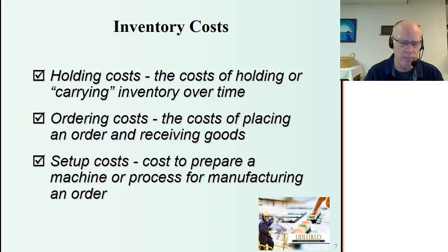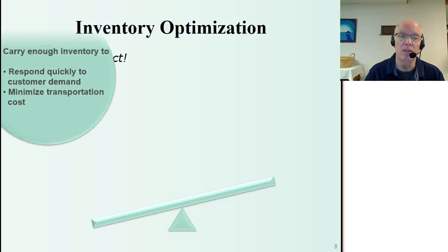So if I have a block of material coming in, the typical scenario is I'd like to minimize my inventory. But if I have setup costs, so for example, if I'm building product A and I need to switch over to product B, well, there's a cost associated with that. So I have to balance that. I might say, well, I might make more product A before I switch over to product B because I don't want to have to go through the setup twice. So I'll build this week's A and next week's A before I build this week's B because I have the time, I keep up, and it eliminates an additional setup charge. So inventory is a balancing act.